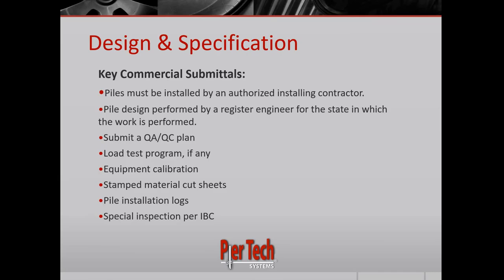And they'll also do a QA/QC on the piles as well by measuring and making sure the pile material is what it shows on the working drawings. And they'll also verify depth of installation, the tolerances, the cutoff elevation, all of those key elements for installation. That's the purpose of those special inspections.